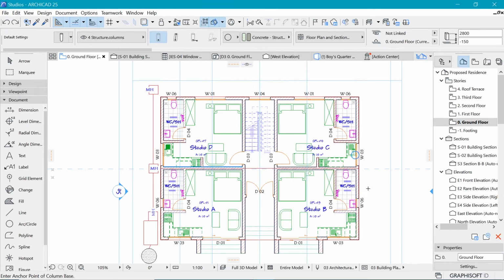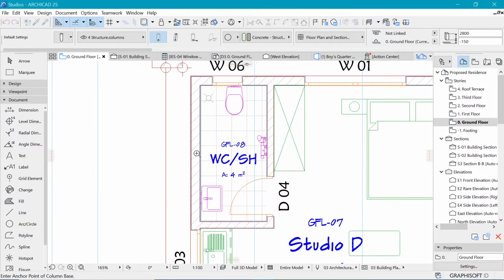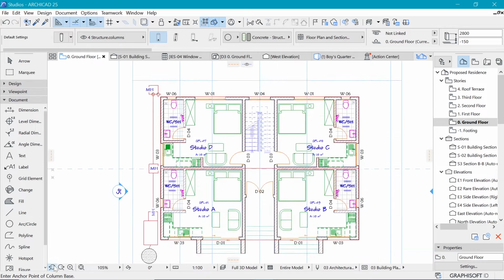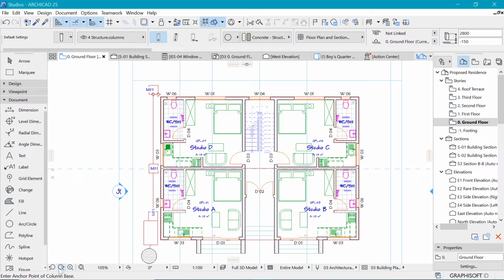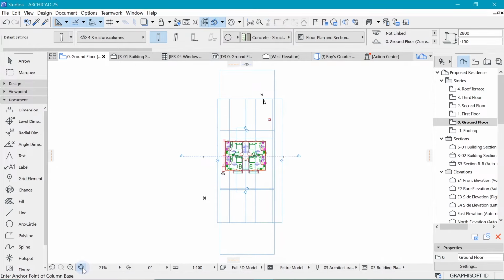And then to the bottom, we have what we call the Quick Options here. You can see there is Previous Zoom, Next Zoom. We have the Zoom tool. If, for example, I click on it and zoom to this area, it will definitely take me to that. And then if I click on Previous Zoom, we go back to where we were. Next Zoom, Previous Zoom. So you can navigate between those two. And then there is Fit to Window, which will fit everything that you have drawn in the same window. And then we have the percentage representation.